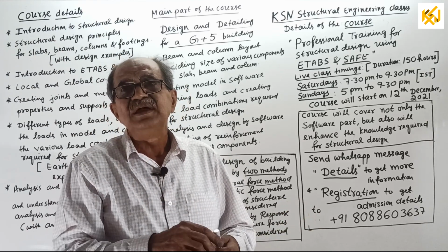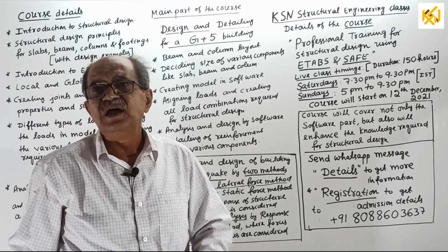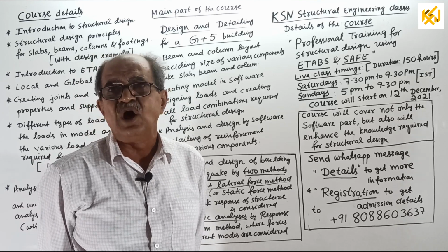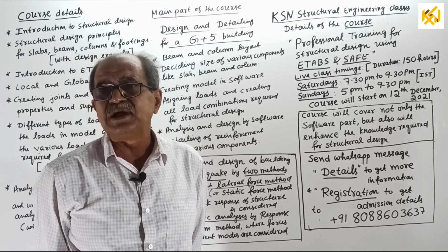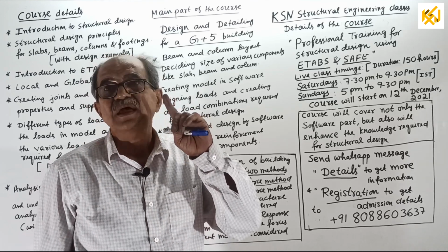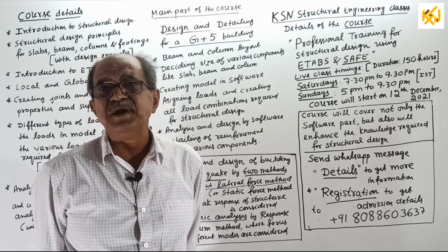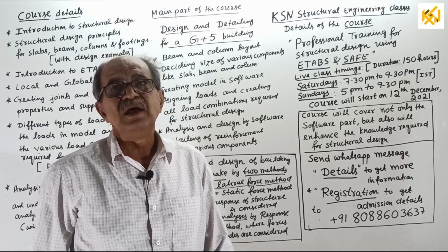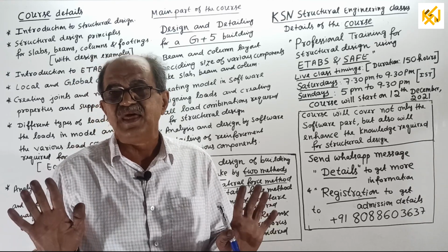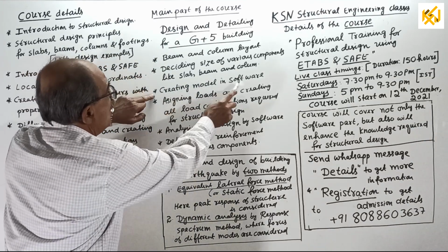Structural design means deciding or designing the cross section to resist axial force, shear force, bending moment and torsion, among those whichever comes. And also very important, the cross section provided should meet the serviceability requirement. So remember, therefore, design means always deciding cross section. That's all.